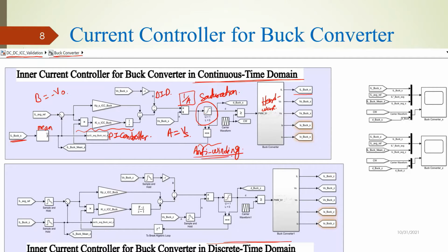So anti-windup is very, very important when you are implementing the control. Basically, when you are out of the boundaries of the saturation block, then you would not like the integrator to integrate some false value, right? So it's very important to disable our integrator when we are outside the saturation boundaries, so that our integrator does not accumulate some false value. And if you do not do that, maybe in this implementation you do not see much difference, but believe me, it makes a huge difference to have anti-windup.